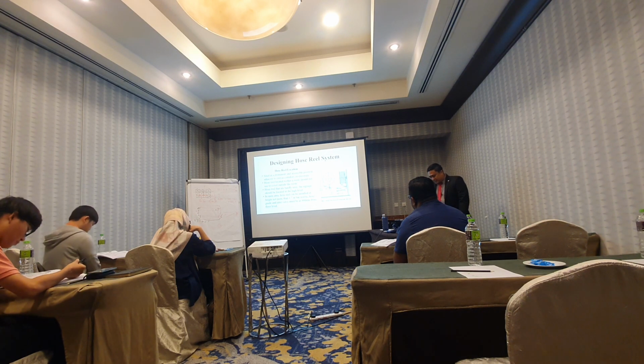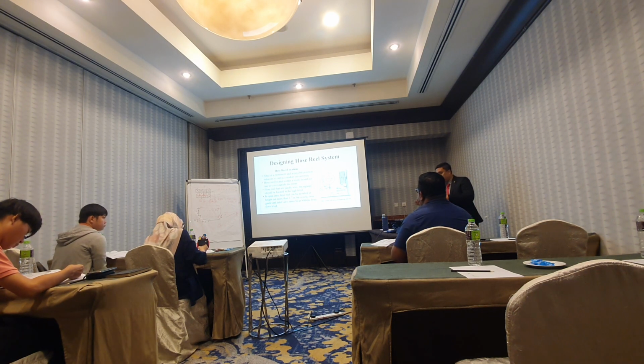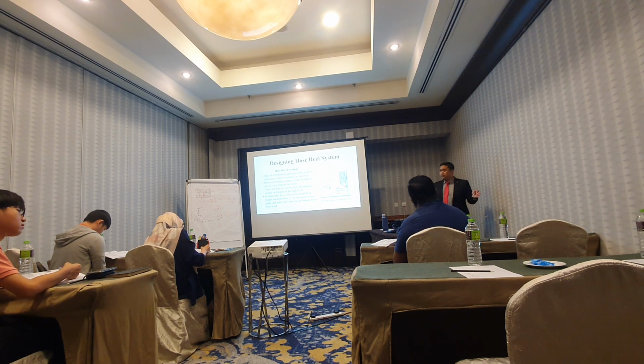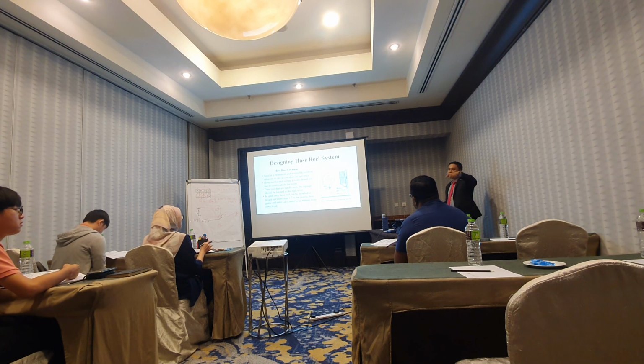Hose reel located within a room should not be used to cover outside the room. Maksudnya, if we install a hose reel within a room, for example, in this room, we can open the door, there is a hose reel inside here. The hose reel inside this room that covers throughout the room cannot be used to cover outside of the room. Maksudnya kawasan luar tu you need to have another hose reel to cater for the area lah.